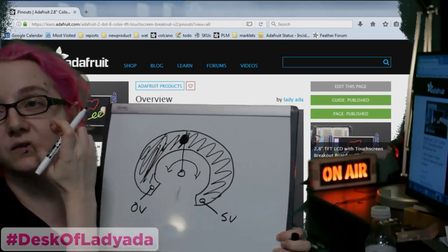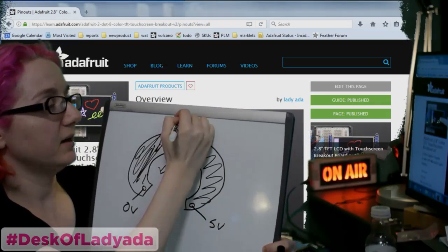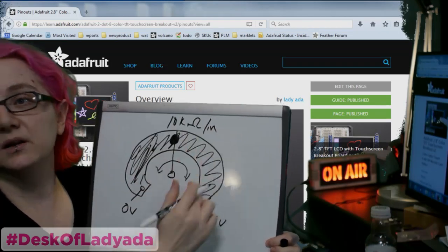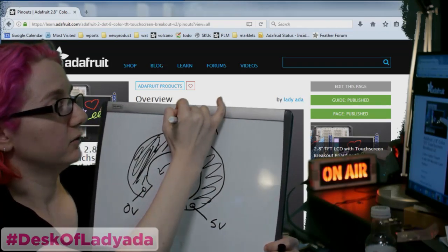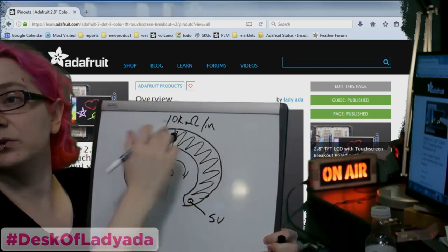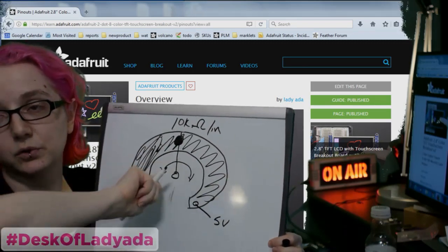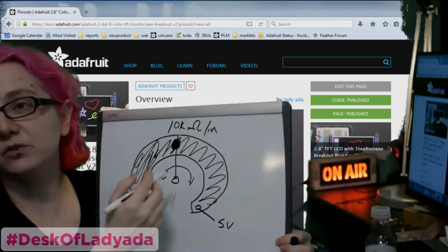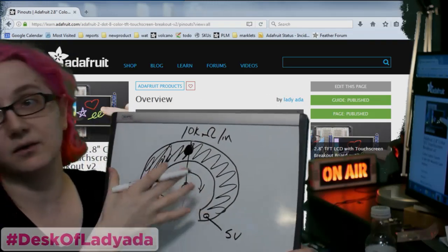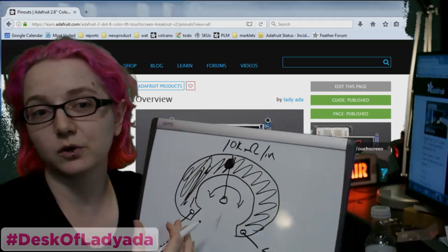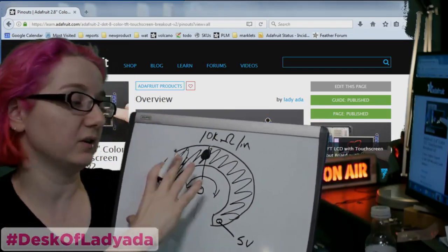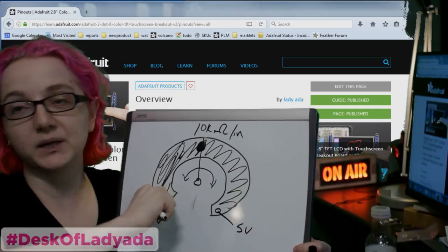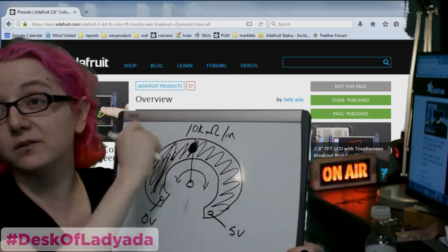And they pick the resistive material so it's like 10 kiloohms per inch. Right, and so this is 1 inch total length, and as you wipe along it, you'll get different resistances. The resistance will change from 0 to 10K, and of course you can get 1K per inch, a smaller resistor, or you can have 1 megaohm per inch, and then you'll have a really big resistor. And if you have a really old stereo, sometimes it gets really scratchy because the wiper scratches away that resistive material.